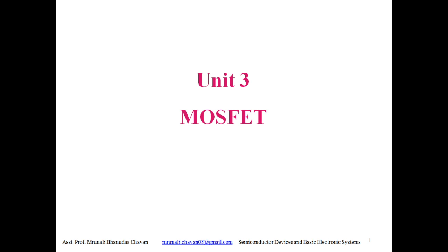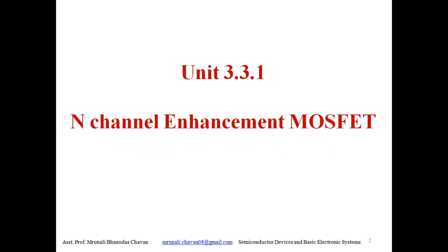We had started our new unit, that is MOSFET, and in the last lecture we had seen the different types of MOSFET, and in detail we had seen the construction and working principle of N-channel DE MOSFET. Depletion type MOSFET is also known as DE, meaning depletion enhancement MOSFET, because depletion MOSFET operates in two modes, that is depletion mode and enhancement mode. So that is called DE MOSFET.